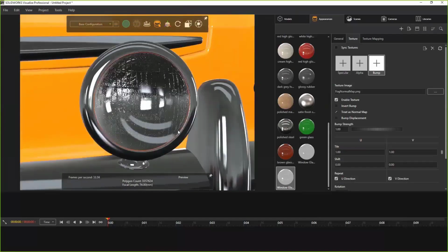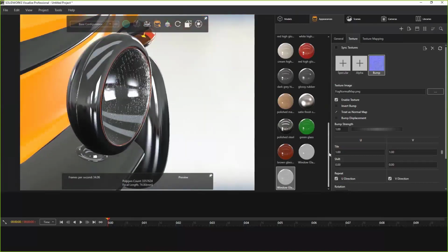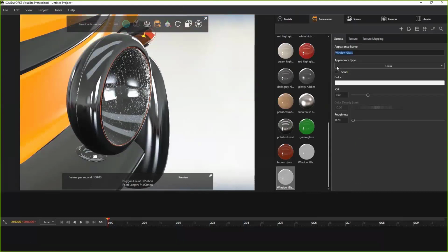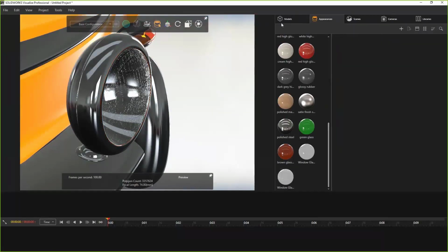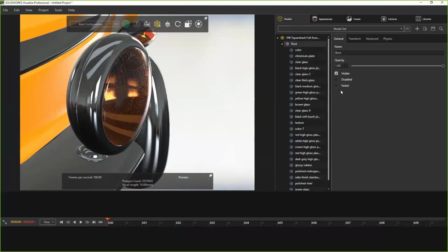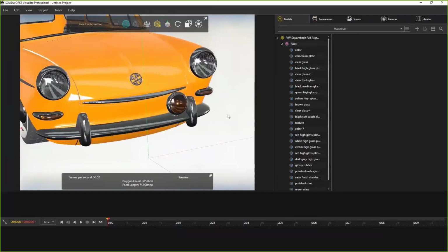And then again, we'll go ahead and adjust the bump strength and the texture placement. So there we go. Again, using the same index of refraction earlier, and we're going to change that color density so it's nice and clear. I want to show those other parts for the lenses, so the front surface, so we get that nice kind of glossy texture on the outside of the lens.